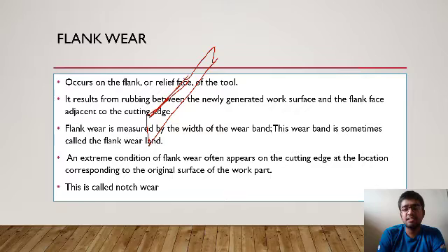Also, the predominant wear is abrasive wear. What is abrasion? Wearing away of a soft material by a hard material. Where is the hard material? As we know, the tool is very hard. Is the workpiece also a hard material? Yes, it can be. Take a situation like a rod obtained after casting. During casting, the casting sand is sometimes included in the workpiece, and casting sand is always very hard. So if casting sand is deposited on the work material, during machining, when the sand particles hit the flank, the flank will automatically wear out, because the sand particle is harder than the tool material.